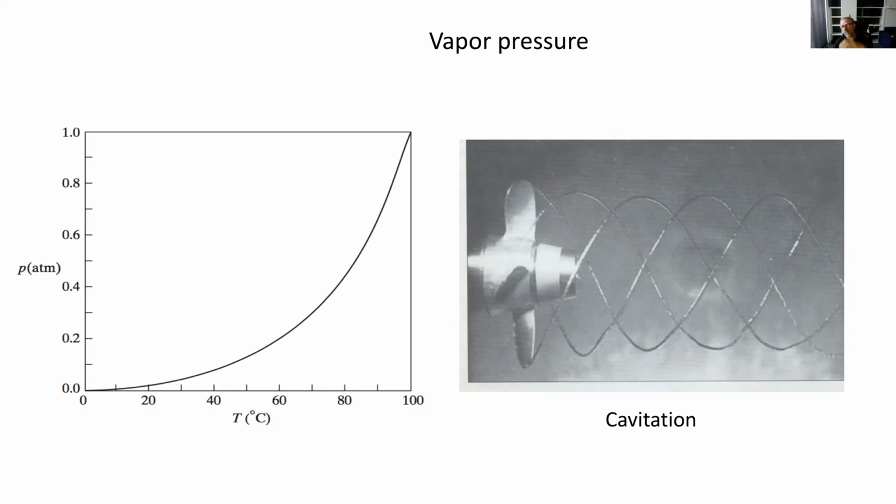So in the cap of your radiator, there's a number, and we chose what pressure the system was designed for, and therefore you can go to a higher temperature. So it's not going to boil at 100 degrees C. That's one of the tricks. Another trick that they do in a car, they put some antifreeze in there, which is not only antifreeze, it's also changing a little bit the boiling temperature. So this is one thing to remember.